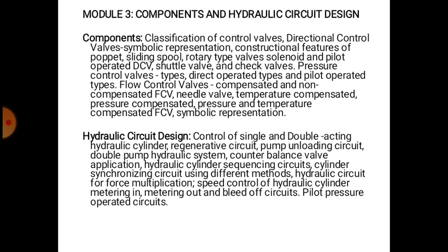The application may be lifting of a load, or punching of a hole in a plate, or moving of a robot arm, or gripping of a component by the robot. So for different applications we must design different circuit diagrams. Different circuits we are going to study: meter in circuit, meter out circuit, sequence circuit, counterbalance circuit, control of hydraulic motor, synchronization circuits. So different types of circuits we are going to study for different applications.